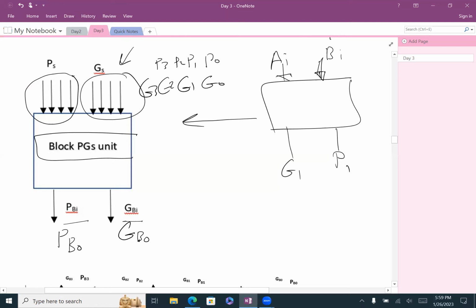Now, when we put the whole circuit together, it will be more clear for you. But we're trying to find how we will achieve the final result. All right. So we'll follow the same steps. We try to find where we generate the carry, because always our problem is with the carry, not with the sum. So here we find where we generate the carry when you have a block of 4 bits. At the end, not the first bit, not the second, not the third, the last bit, where we will have a carry.